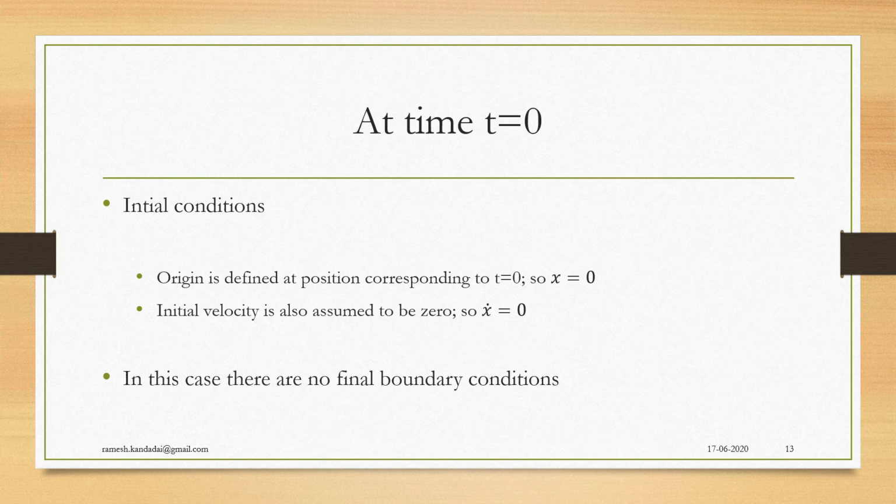At t equal to 0, the spring mass damper system is already hanging at rest. So any static deflection in the system has already happened, and it is taken into consideration at the point at which the system now is at rest. So at t equal to 0, the deflection is defined as being 0. So the origin is at rest, taking the static deflection out of consideration.